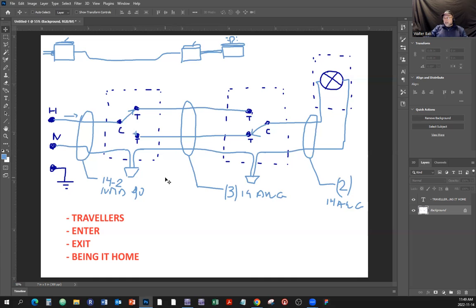All right. So then you're going to pull the wires, run the wires, install the wires, popularly called the wire pulling stage. So you're going to pull the wires from the electrical panel into the first box. You're going to cut it off, leave it. Then you're going to pull the wires from here to here. And now these two boxes are not going to be 2 feet from each other. They're going to be maybe in different rooms, one downstairs, one upstairs, and it's going to be a long pipe.